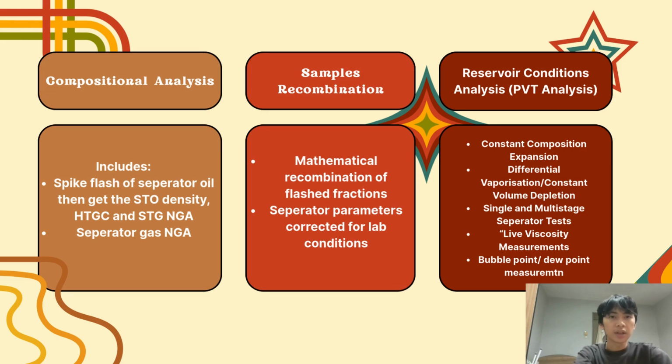Reservoir condition analysis, or called PVT analysis, comprises of constant composition expansion, differential vaporization, constant volume depletion, single and multi-stage separator tests, live viscosity measurements, bubble point and dew point measurement.